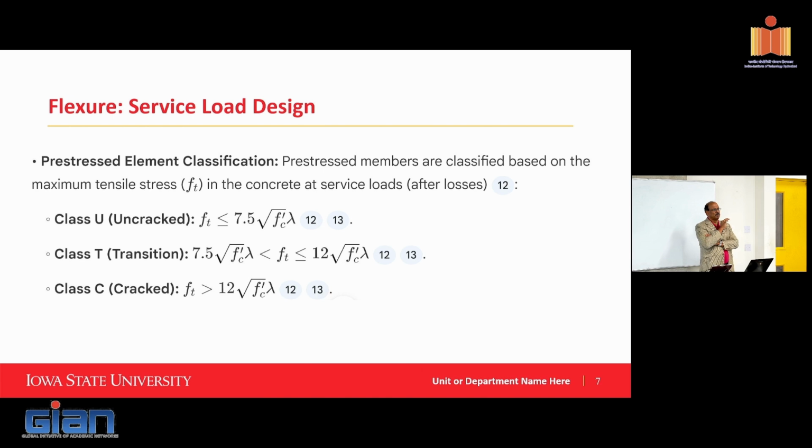In the US, there's a practice where the code specifies what's required, then design guides use phrases like probable strength, what's likely to be the strength, and if you don't see any major challenges, then you're allowed to use that probable strength, right? For example, the structure may never see the ultimate limit state, and making this assumption doesn't cause any drastic negative impact to the structure, then that assumption is fair. So anything that you do as a designer, you should be able to defend as to why you did that, right?